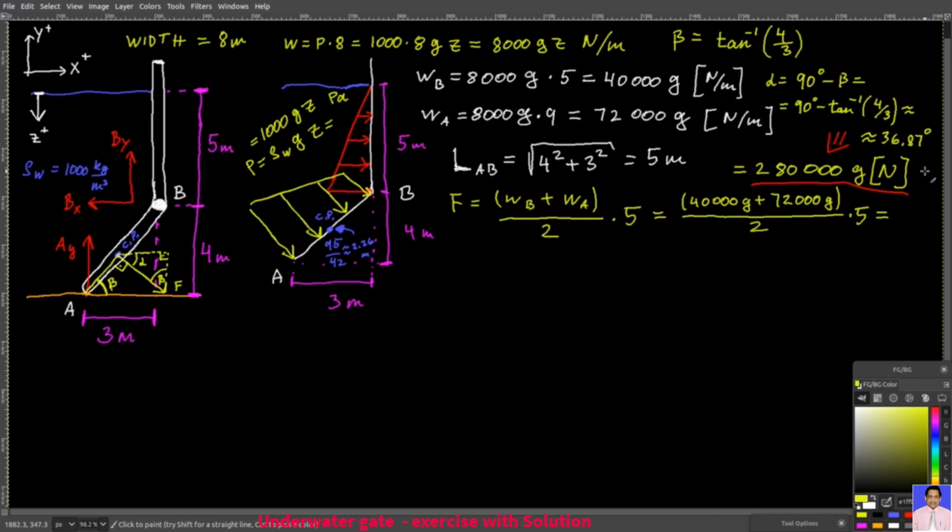And now you have 3 forces here, AY, BX, and BY. They hold this gate at rest. The gate does not translate, which means that in this case, the sum of all the forces in the x direction is 0 newtons, and also the sum of all the forces in the y direction is 0 newtons. And this gate does not rotate either. And that means that the sum of the moments is also 0. And it does not matter what point you take your moments about. To keep your gate from rotating, the sum of the moments about any point must be 0 newton meters.